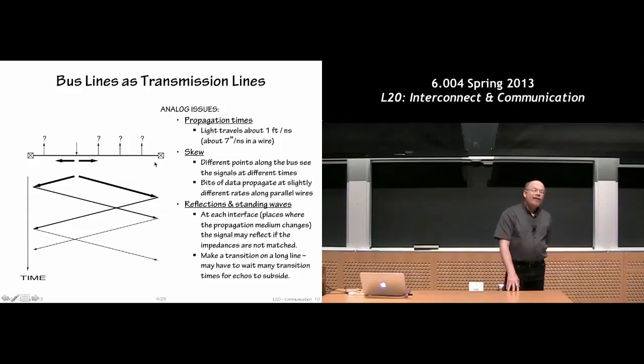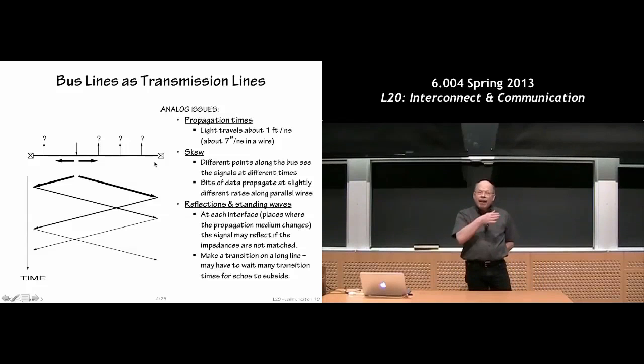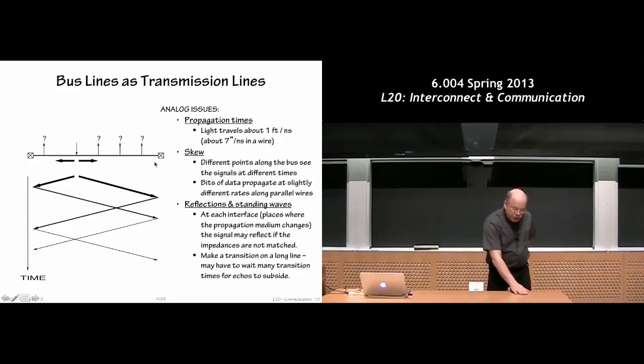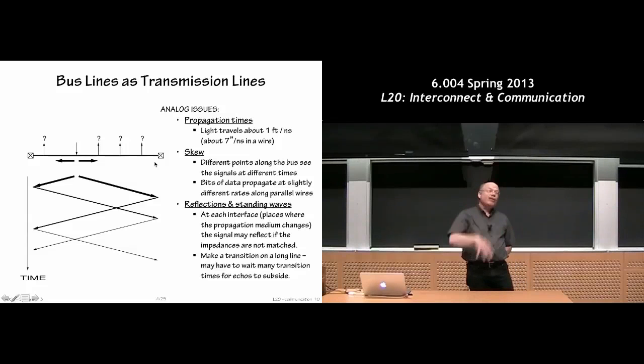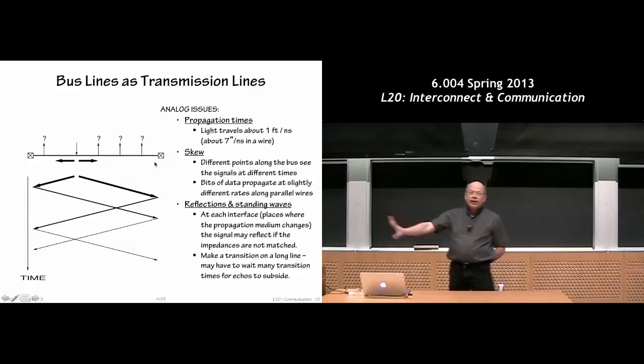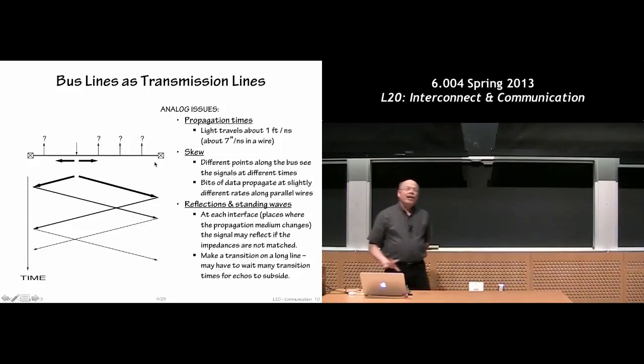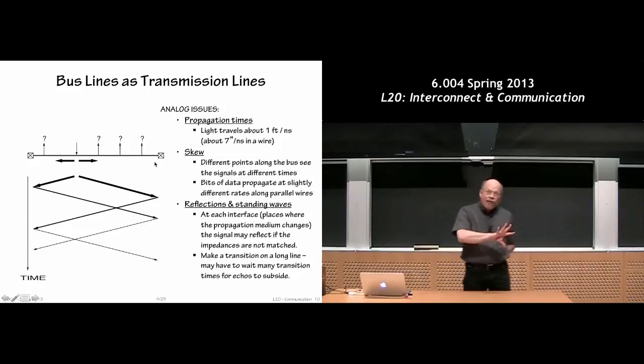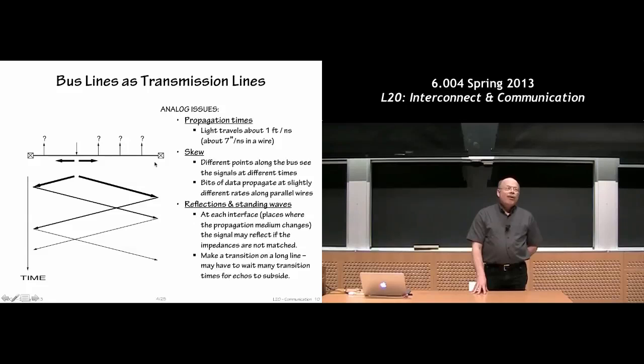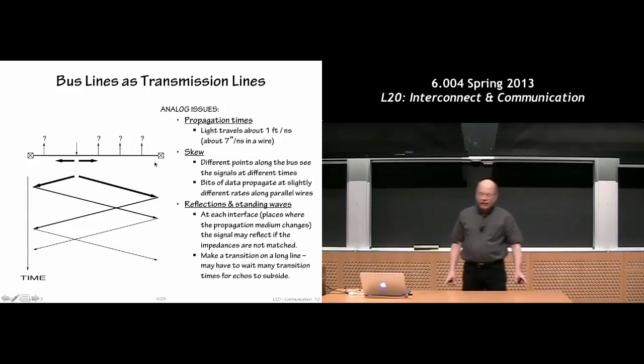And if you take enough E&M, you begin to realize that the propagation of a voltage, I changed the voltage from 0 to 1, so I'm changing the electric field. The propagation of that change in electric field down this conductor depends crucially on the impedance of the conductor, how fast that goes. And more critically, if there's a change in the impedance, a little bit of the energy of that transition actually reflects off of that and starts traveling, making its own journey around the bus.